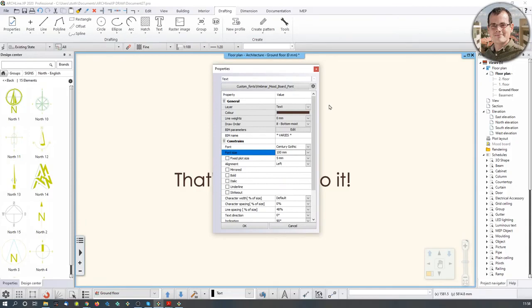When you are creating a plot layout, the plot layout is not there to get additional text or lines on top of it. That's just for collecting the elements. If you want to have additional annotations, you can do that just fine, but the role of the layouts is not to have actual elements, additional drawing elements onto them. It's about collecting things. So if you want to have additional text, you can do that, but it's better to make them in the 1:1 scale floor plan view.